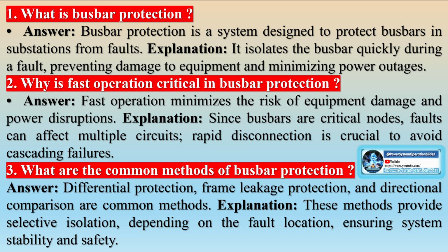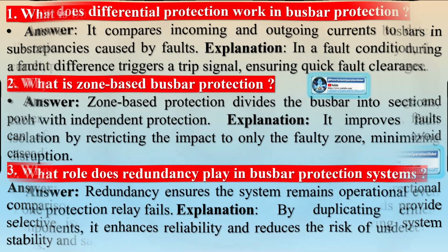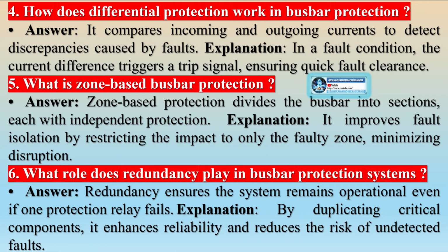Circuit breaker failure protection operating principles. The overcurrent relay confirmation is essential for verifying that a circuit breaker has interrupted the current and provides security against unwanted start signals, especially during testing. For feeders with weak infeed, the circuit breaker auxiliary open contact 52A is often used instead of current-based confirmation. The time delay is set according to network stability requirements and is crucial for coordinating with remote backup protections.